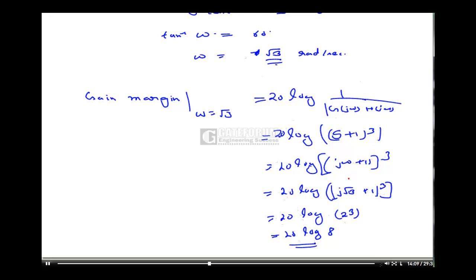From this we can find out about the stability and instability. So just for a note, you can write, for a stable system, gain margin and phase margin both should be positive. Okay, since this problem concerns finding the gain margin, but if a problem is concerned about finding the phase margin, it must be positive for a stable system. While solving the problems, we will take care that the variety of problem is not repeating. Okay, now another problem.